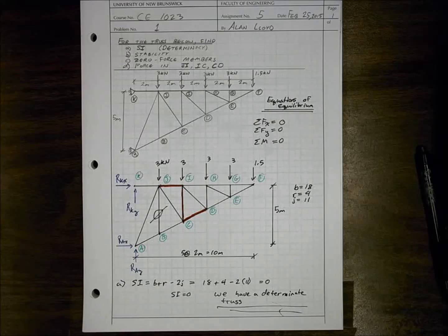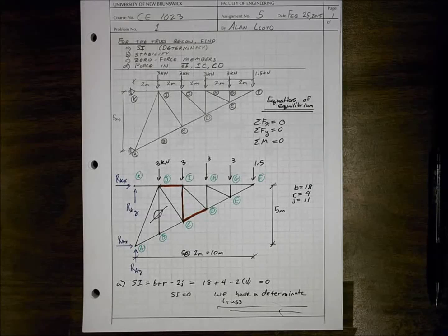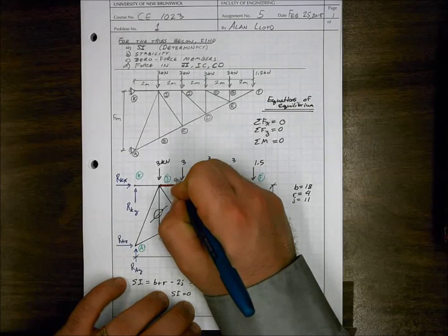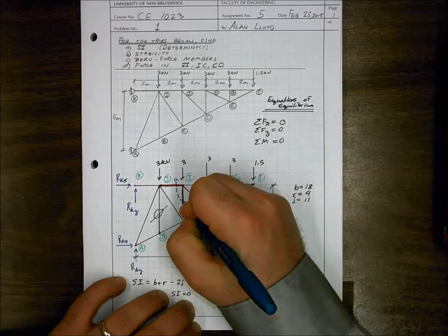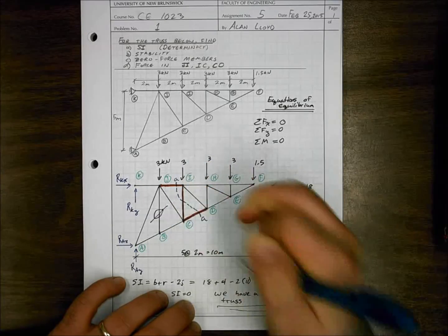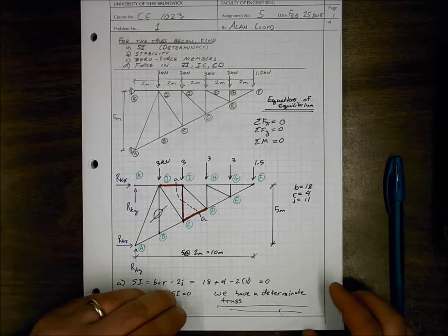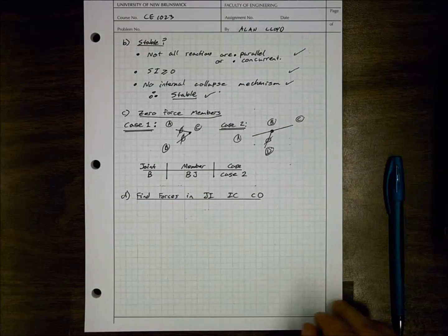The goal of this is to, as quickly as possible, solve for all of the missing values that we want to find. So here we're only after 3 member forces, and if we have 3 unknowns, we have 3 equations of equilibrium, we can solve it immediately. So let's give ourselves locations AA, and we'll pass a cut, as shown here, through the members that we don't know. And this exposes 3 member forces, and since we have 3 equations, we can directly solve for this.